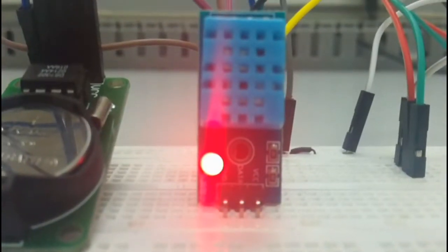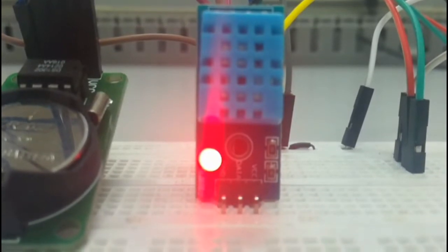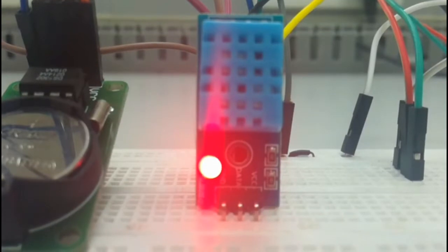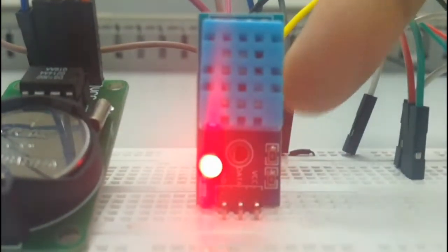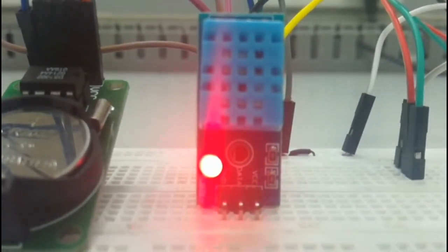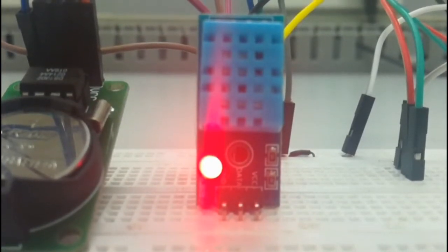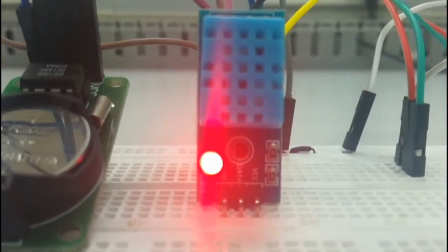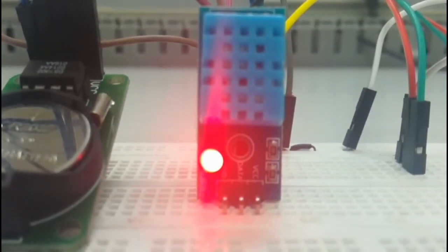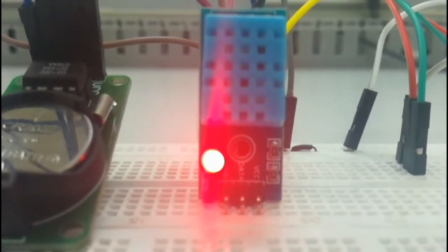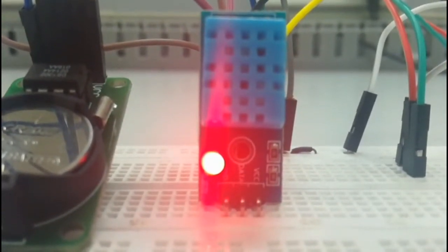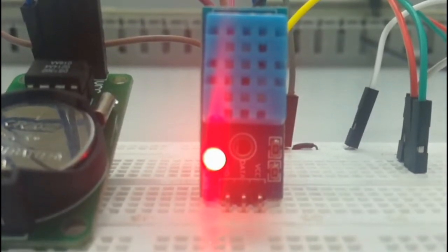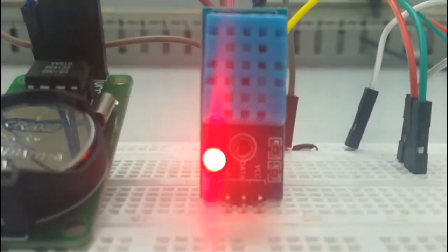The DHT11 consists of two sensors, which are a humidity sensor and an NTC temperature sensor. It also has an IC on the back of the sensor. The humidity sensor uses a humidity sensing component, which has two electrodes with a moisture holding substrate between them. When the humidity changes, the conductivity or resistance of the moisture holding substrate also changes. This change of resistance is measured and processed by the IC.